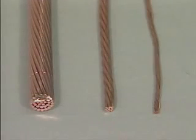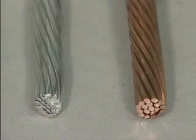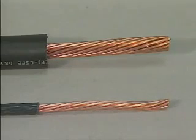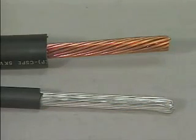The size of a wire affects the amount of current that it can carry. In general, the larger the diameter of a wire, the more current it can carry. But materials vary in their current carrying capability, so the composition of a wire, that is to say the type of material that the wire is made of, also affects the amount of current that it can carry. Together, the size of a wire and its composition determine how much current it can carry. The amount of current that a wire can carry without overheating is called its ampacity. If you double the size of a wire, you also double its ampacity. On the other hand, two wires that are the same size but made of different materials will not necessarily have the same ampacity.